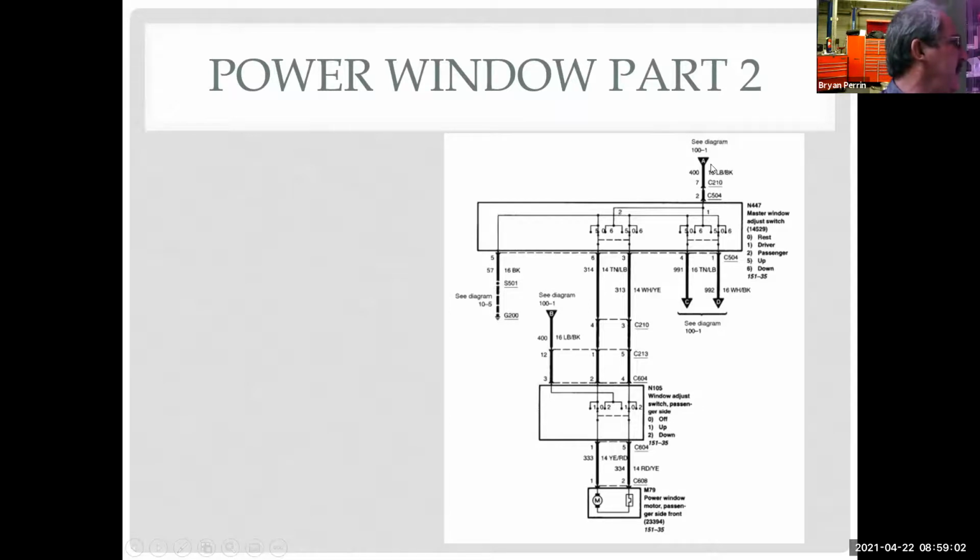So if I look at A, it comes down, has a splice, and it goes what? Into the center here. It also comes over to the center here. Okay. Well, what is on the outside? Well, I have ground here. So ground comes up and it's on the outside here, here, here, and here, which means A has to be what? Battery power. Okay, because I've got two things, I've got power and ground.